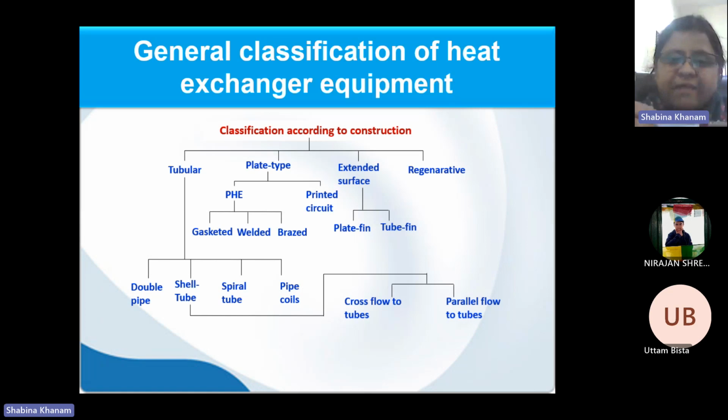So if I have this inner tube, the strips will be welded like this. I am considering this as a plate type, not a tube type. So that plate would be welded over here, over here, and over here like this. Along the outer periphery, plates will be welded at a regular interval, and that we call fins.